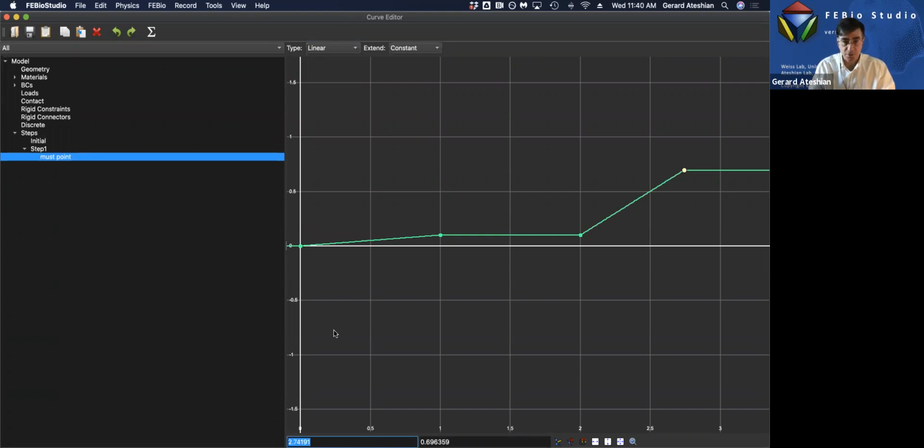well, actually, before I do, I'm going to change this point in a moment, but because I changed this from step to linear, I'm going to go back and make sure that my time increment at time 0 is also 0.1. This way I have a constant time increment for the first 2 seconds. And then up until time 100,000 seconds, which is 10 to the 5, I want my time increments to go linearly up to an increment of 10,000 seconds.